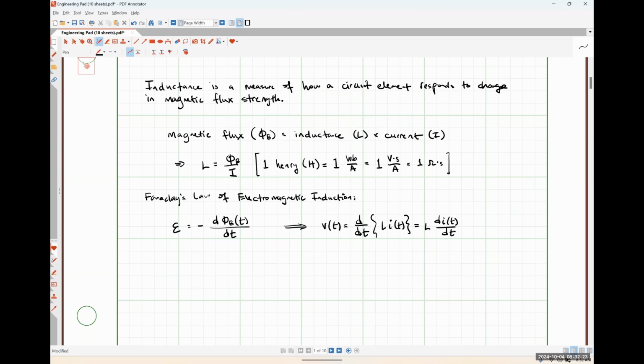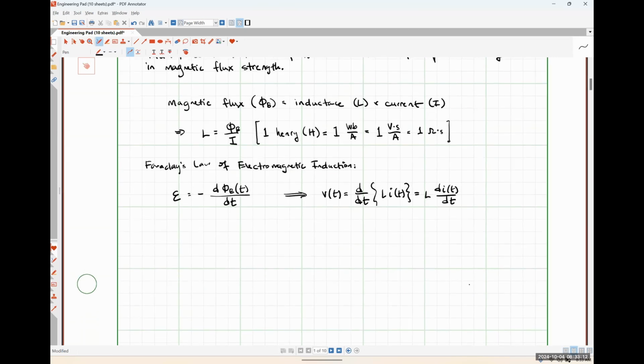So what happens is the air between the terminals of the receptacle actually becomes ionized, generating a plasma that allows current to continue flowing for a few milliseconds, microseconds, nanoseconds, depending on what the inductance is, to make sure that that flux gradually decays instead of abruptly decays, because as we'll find out here in a couple of minutes, that would literally cause an infinite voltage to appear, okay? So anytime you ever unplug something and you see sparks, that is literally Faraday's law of induction in action, trying to make sure the flux doesn't change abruptly. Okay. So we have our mathematical relationship. This is one of many. I'll come back to it in just a moment.